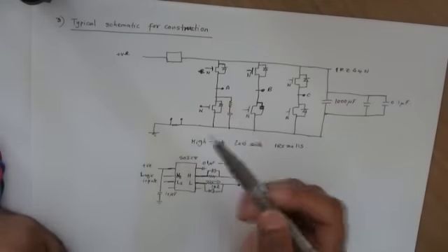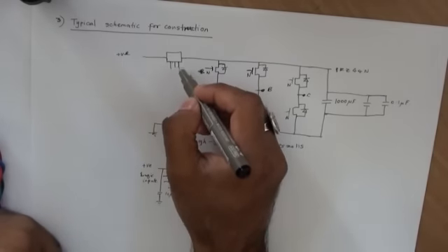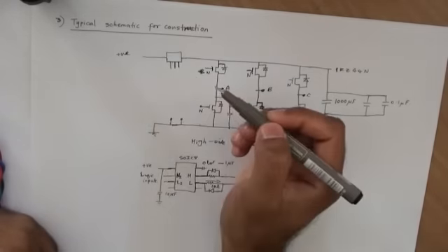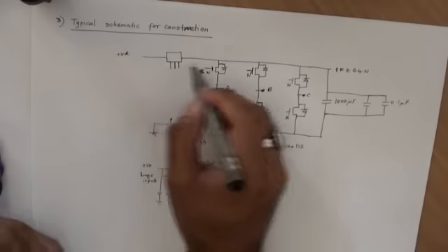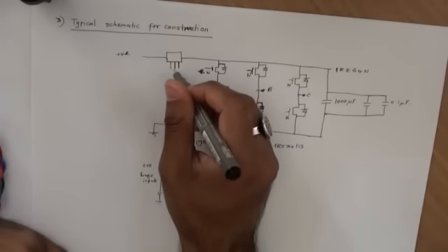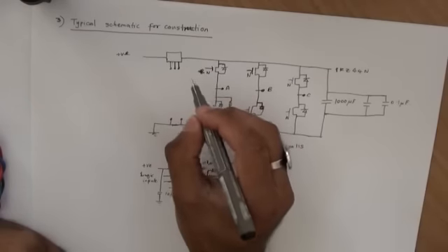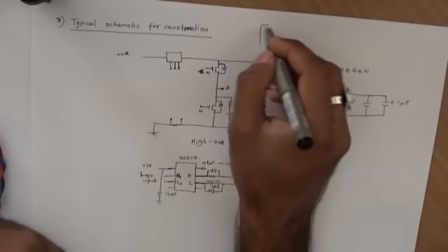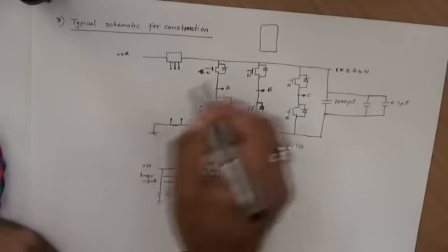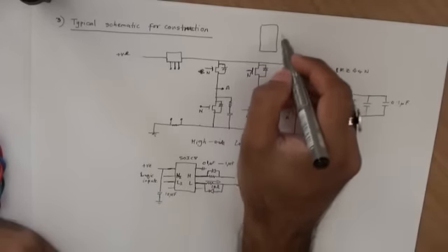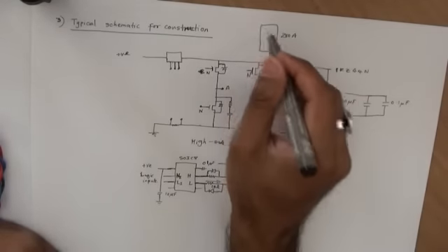I then found a good solution provided by Allegro Microsystems. They are providing current sensor chips where you basically pass the current, you consider it as if it was a resistor, and they provide analog outputs from the module. So it's a module no bigger than about this size, depending on your current requirement. A module of that size will give you up to about 200 amp. If you check out their website, you will find that they have these devices.